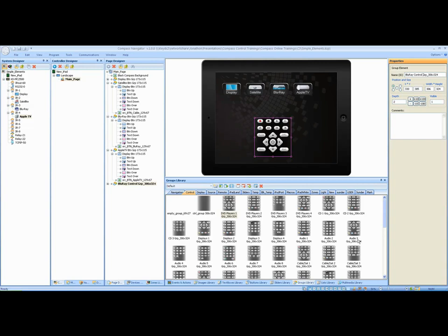our, let's see here, cable satellite we have. So how about this one here? And what I'm going to do is I'm going to now drag this cable satellite, and I'm going to drag it into the exact same location, which for the Blu-ray control group is 330 on the x-axis, 385 on the y-axis. And again, why I'm going to do this is really going to be something where we work with the visibility tricks in C3 part 3. So I'm going to take it and roughly drop it to the same place. This is for our satellite box.